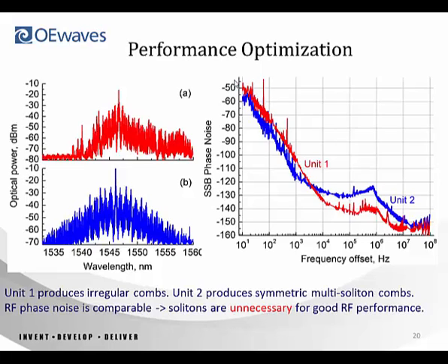But if you look at the phase noise picture, you can see that at small offset frequencies from the carrier, phase noise is not so good. It is worse than the mode-locked regime, but at higher offsets it is better. And frankly speaking, it is not very clear why. But it is interesting that it is possible to play with the system, and sometimes observation shows better results.